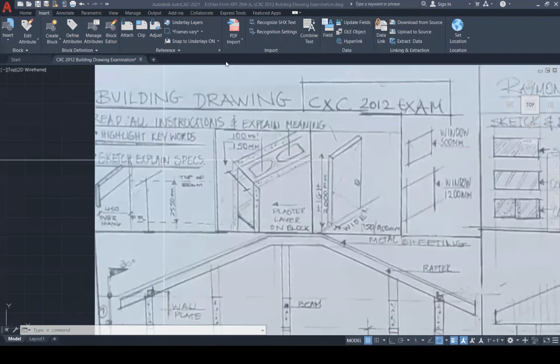And this is it here. So this is a concrete block wall right here. And it has the plaster on both sides. Plaster is here and the plaster is here on both sides, right? So this can either be 100 or this could be a 150. But what is important is the plaster on both sides. And the plaster is usually 10 mil on each side.